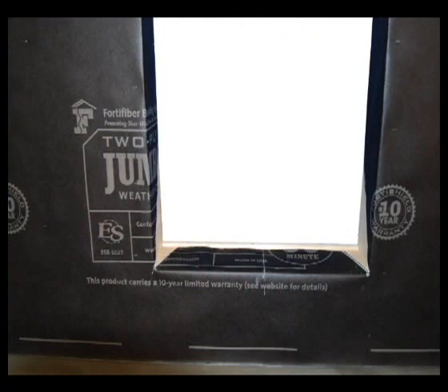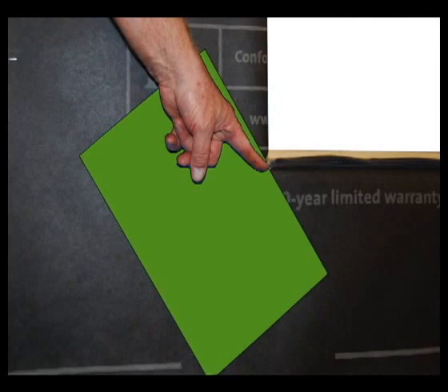The WRB should be cut with the inverted Y method so as to fold over the bottom inside of the window rough opening. Using the inverted Y method, the WRB will also fold over the sides and the top of the window rough opening. Pieces of waterproofing material or flashing should be placed on each side of the bottom corner of the rough opening on the face of the wall.